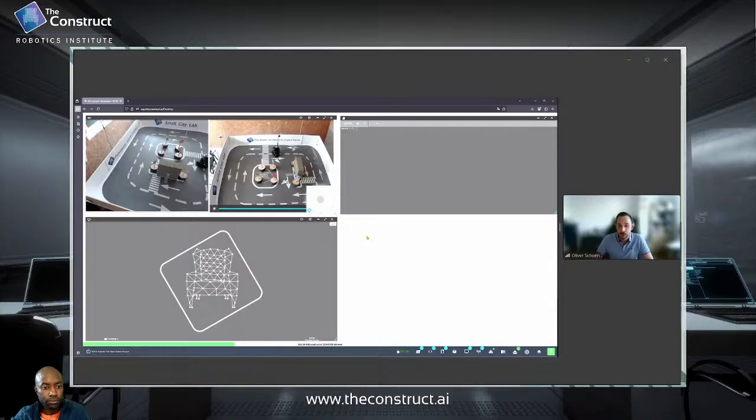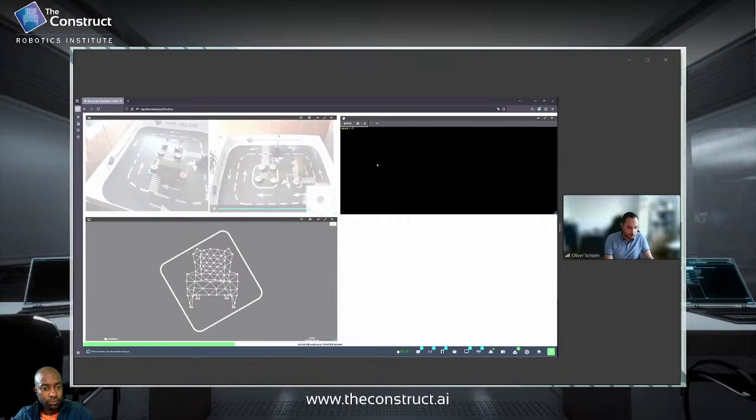And for that, of course, first we need a robot description file, a description of the robot, how it looks and how it's actually set up. And to show that this does not exist yet, I want to quickly check the published topics currently. There are a few topics published, for example this command velocity we use for commanding the robot to move. We have the joint states of the robot, so that is all the things that the robot is already publishing and providing to us. But you cannot see any robot description yet. So let me check here, there is no robot description we can use.